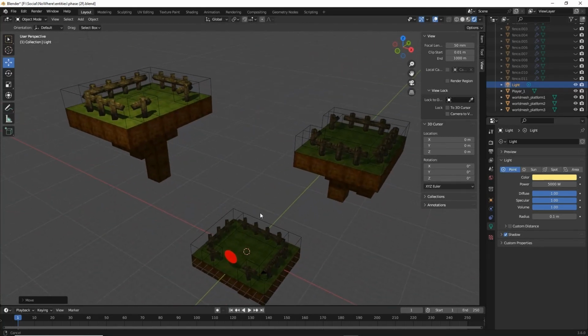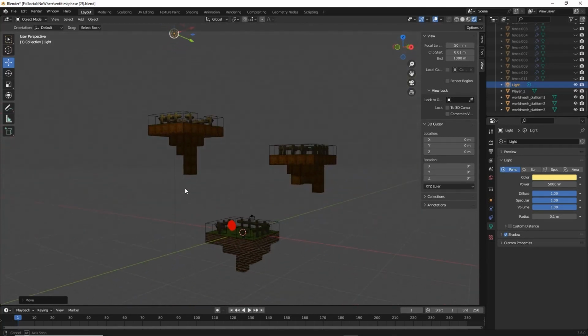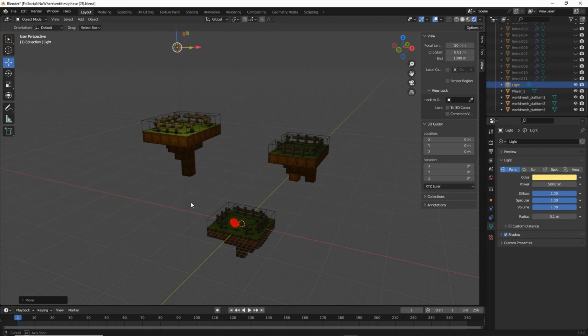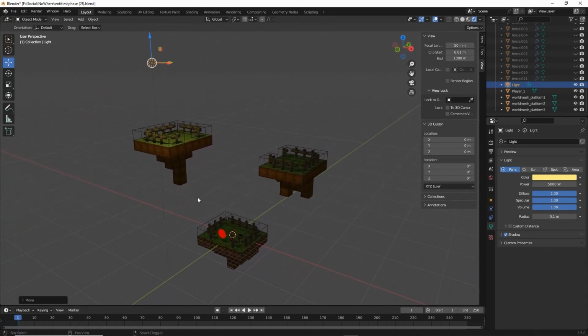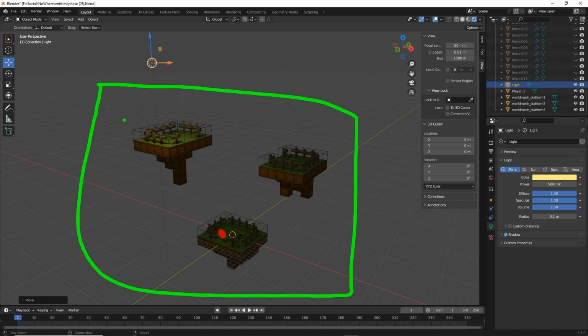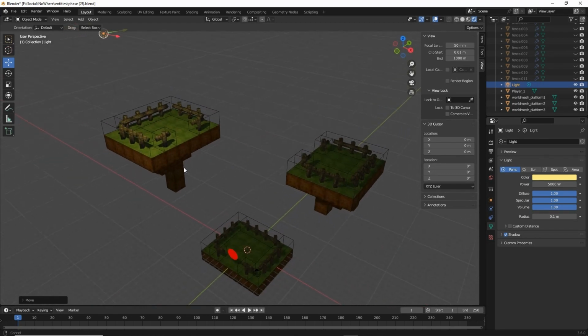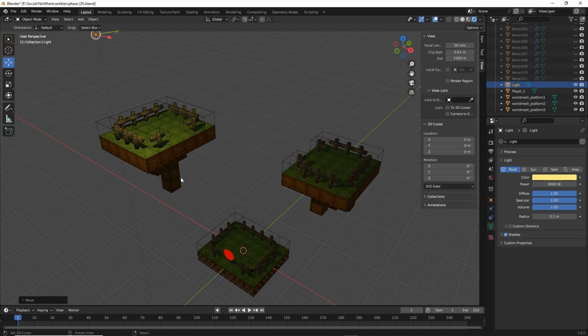So we could do an export test at this point, but one thing we might want to do is add a very simple skybox around this, because if we don't, the scene will load and it will be white. It'll be a white background. And that'll make the entire scene quite difficult to sort of discern. So we'll need some textures for this. Well, one texture basically. So what we'll do is we'll create a box, a big box, and we'll texture that box with the same texture on each face, basically a sky blue, and that will be our skybox.